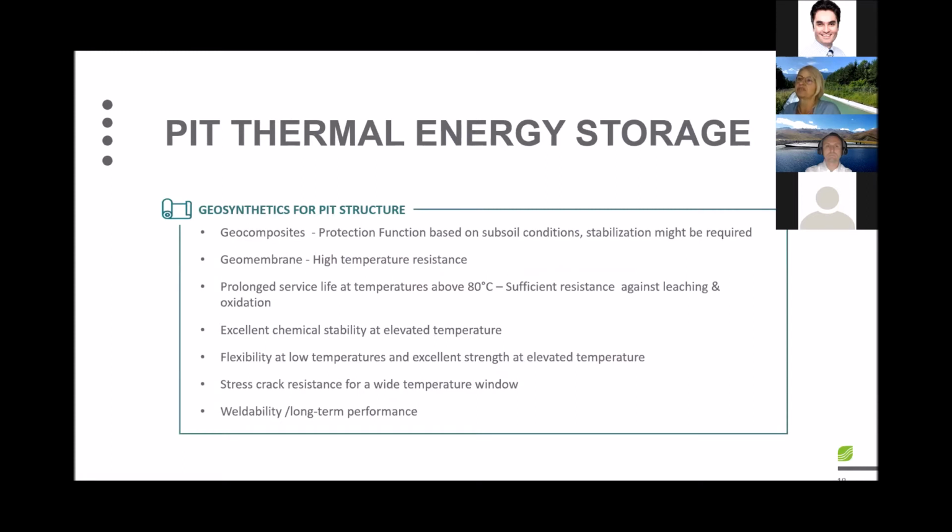So which geosynthetics go into such a pit structure? Protection layers can be geocomposites, but can also be geotextiles only. The protection function is, as I said, based on the subsoil conditions, and stabilization layers might be required. The geomembrane used in such a storage application has to be high temperature resistant. This is a key function of that product.